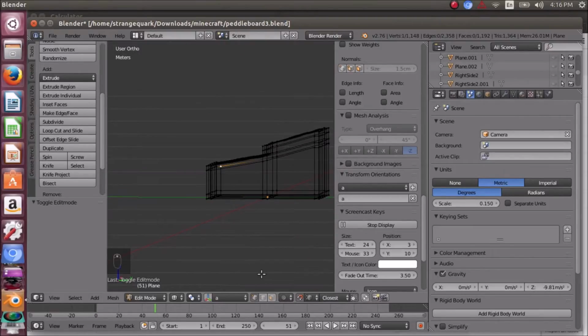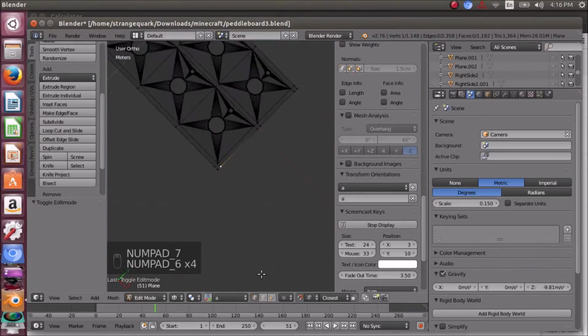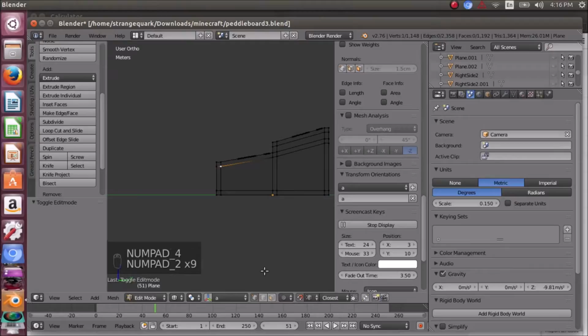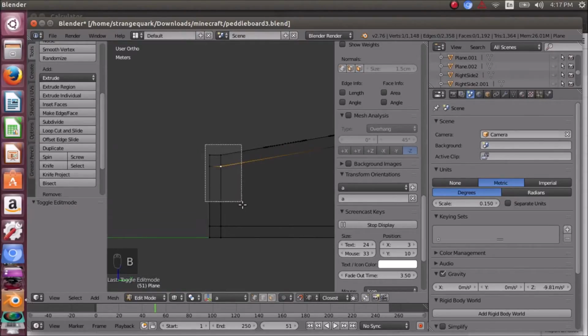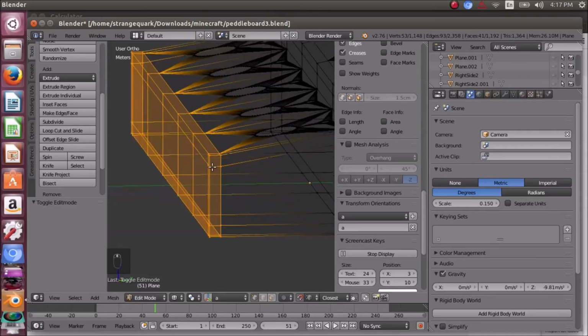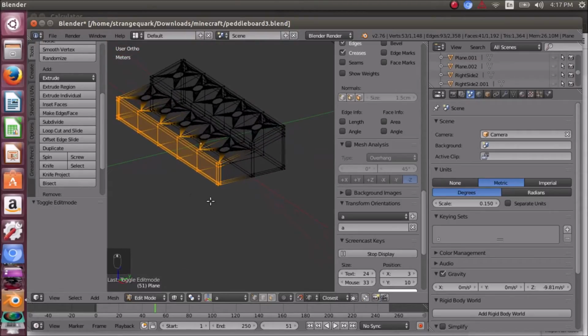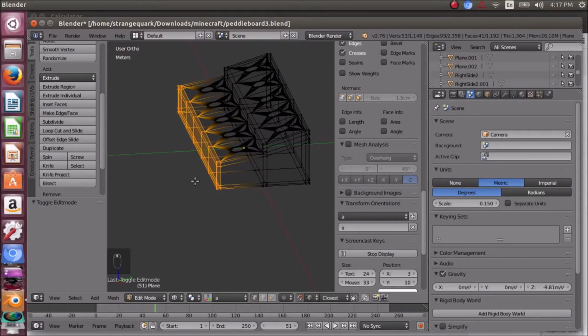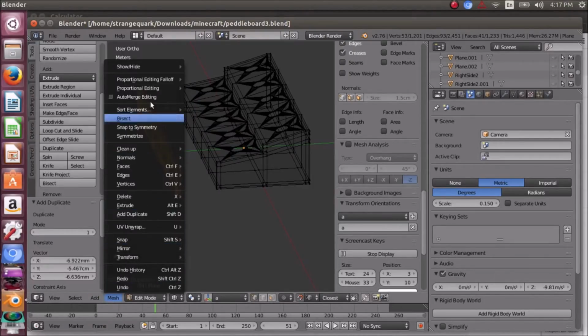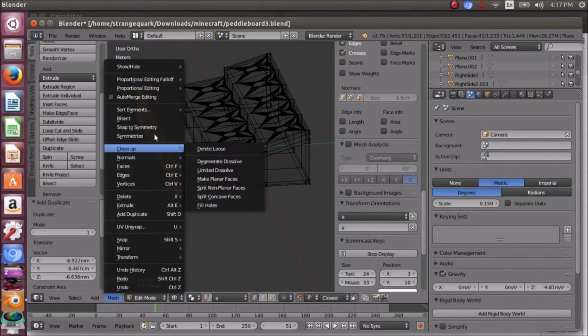So we'll go ahead and select this other plate, this front plate right here. I'm going to hit box select, and again, we're in vertex select mode. So this is what we're showing for that plate. I'll go ahead and duplicate it, hit Shift D, and then separate it. Let's see, separate by selection.